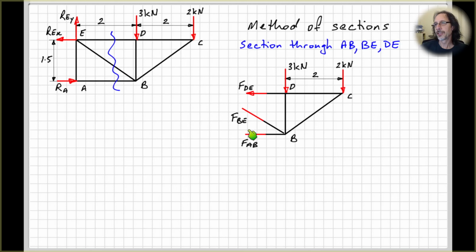Right, so now let's look at the others. So we've got force going in this direction and this direction, so we can't immediately tell from horizontal forces which way these are going, but from looking at the vertical forces, we've only got this one with a vertical component, force FBE, plus our 2 applied loads. So therefore FBE must be acting upwards to the left.